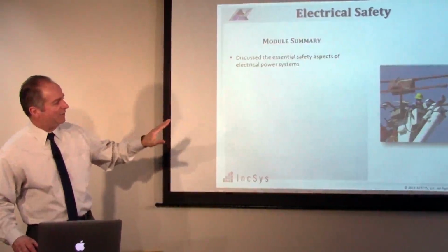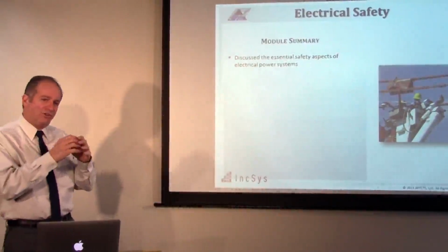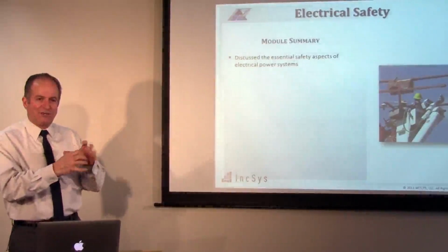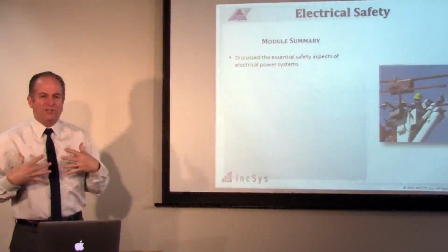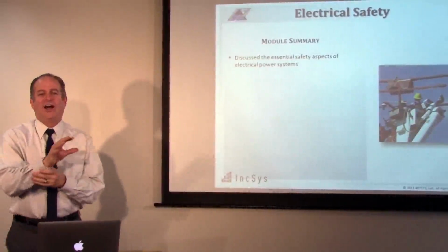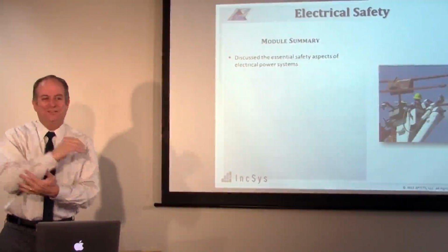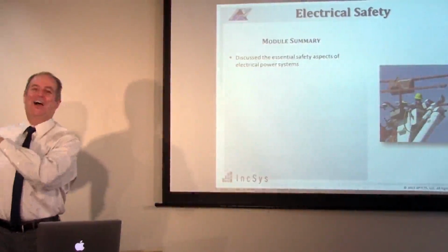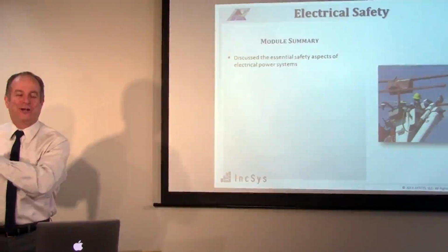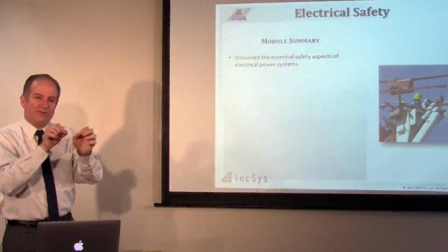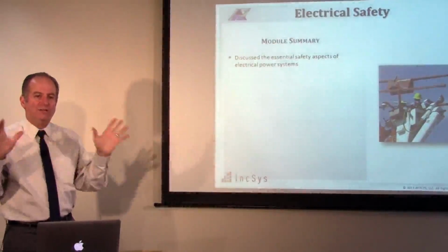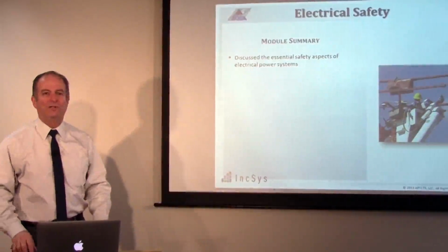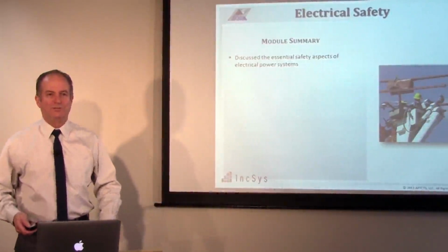All of that equipment is covering up so that you can do surgery, in a sense, in one exposed area. With the rubber gloves and arms and all the protective equipment around you, it's designed so that if you accidentally touch something, you're going to be okay. It's not designed so that you can hold on to an energized wire. It's really: we're going to work on this energized piece, get that work done, and move on. I want to make that clear.